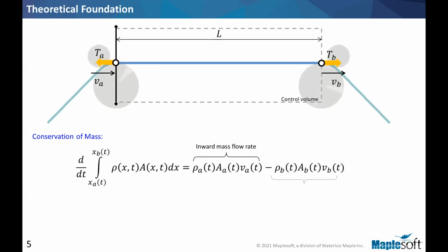And the other one obviously is everything going out. So we're accounting for the change in density, change in area, and change in velocity. If we have the material coming in, subtracted from the material going out, this is the flow rate of material. So what we are left with is the rate of change of whatever is inside, and that is done by the integration over the span.